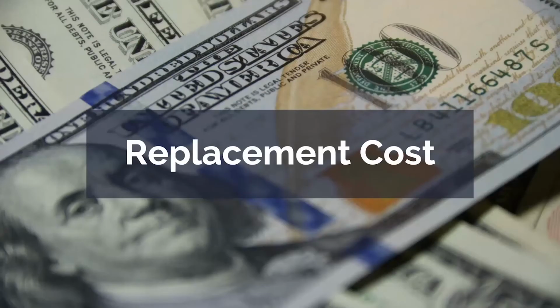Obviously, a related piece of information is replacement cost. Going to be critical for future planning. This is not what you paid for the asset when you put it in, but what it's going to cost to replace with whatever model you're going to put in. So if you have old mechanical meters and you're going to replace them with the latest iPERLs, it's the cost of those iPERLs plus installation.